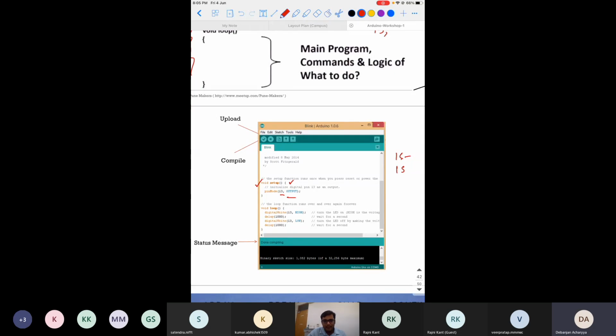OUTPUT is a special keyword in Arduino used in the pin mode function to determine which pin it should control and whether that pin should be an input or an output. If you write INPUT instead, that means on pin 13 you will get input data.